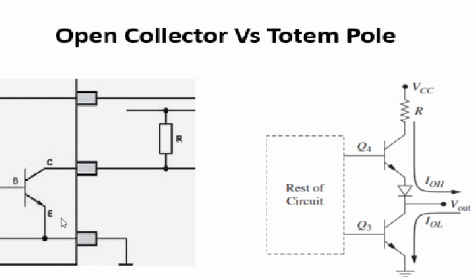So I will be going with open collector for most of what I'm using. In that situation, a transistor's base and emitter junction will drive the collector emitter junction low, and for a high output, an open on the base will just simply leave the collector floating, and this external resistor will pull it high. So multiple gates sharing that same bus will all be pulling the current for that one resistor, and that will mean that it doesn't matter how many devices are pulling it low, the current will only get lower, not higher. So that's what I will be going with.